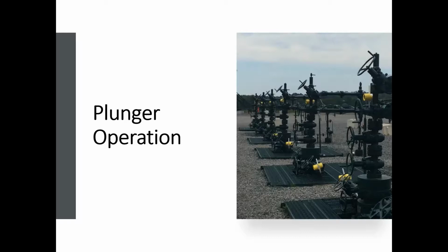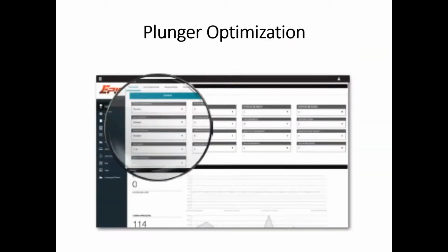Plunger lift optimization requires a combination of consistent plunger cycles, adequate drawdown of the well, steady production on the well's natural decline curve, and optimal total gas rate to optimize the system. When optimizing your plunger cycles with an EPIC controller, the A stands for arrival and the F stands for failure or a missed run. The goal is to have all cycles in arrival and to have their arrival times consistent and at safe travel speeds. Just because we're making runs doesn't mean they're the most efficient runs. We want to make sure there's fluid on top of that plunger.